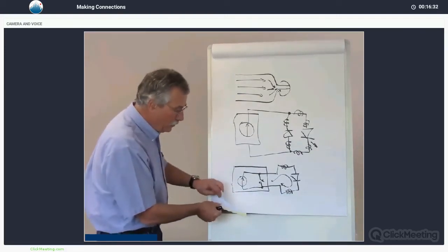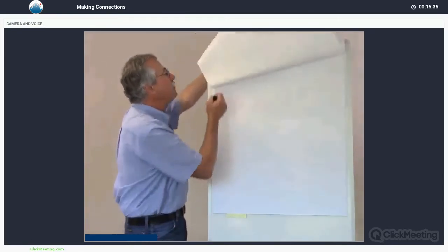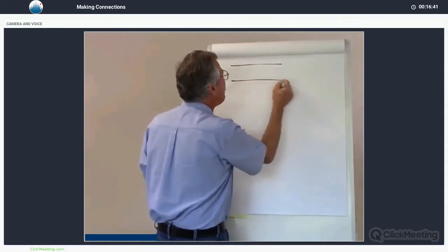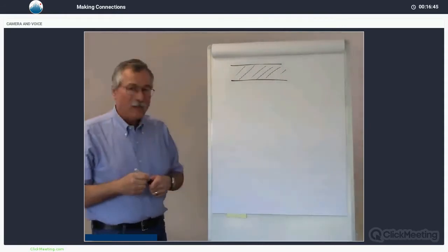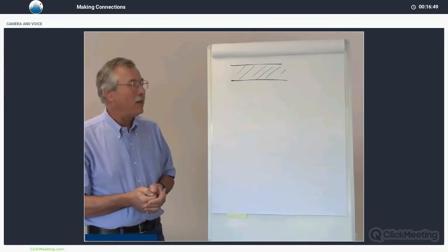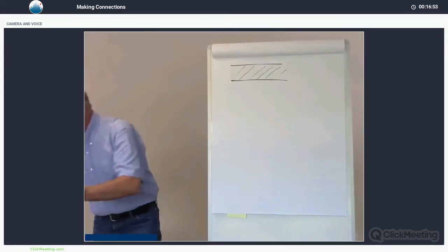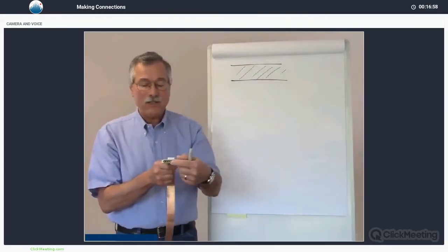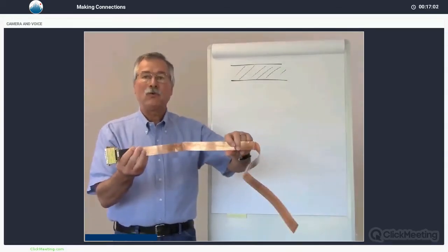So, how about things that do work? Well, the thing that works the best is the thing that has the widest surface area. We call it strip line. It's not exactly the same thing that RF people use to describe strip line, but in our business it's a symmetrical cable. I've got a large one here. We've got a fairly low inductance connector at the end. We have many contacts in parallel. It's about 1.25 inches wide.